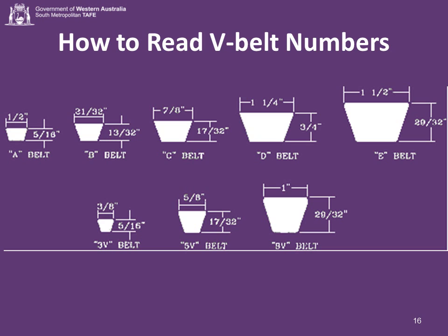Automotive belts start with either 4L, which is 12.5 millimeters wide, or 3L, which is 9.5 millimeters. The numbering following it is the outside length of the belt in tenths of inches. The inside length of the belt is typically 2 inches, 50 millimeters, less for a 4L belt, and 1.5 inches, 38 millimeters, less for a 3L belt.